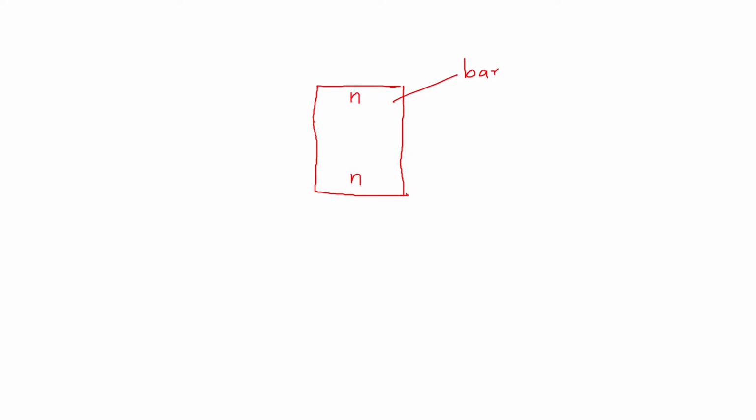In this n-type semiconductor, on the two sides, p-type semiconductor is induced, as shown in the structure. Now here you have p and n, so you will have a p-n junction and there will be a small depletion layer here. Similarly on the other side you will also have a small depletion layer where you form that p-n junction. We know how a depletion layer, a potential barrier, is formed when we studied the theory of the p-n junction semiconductor diode.